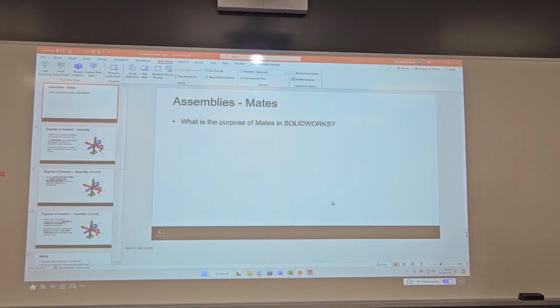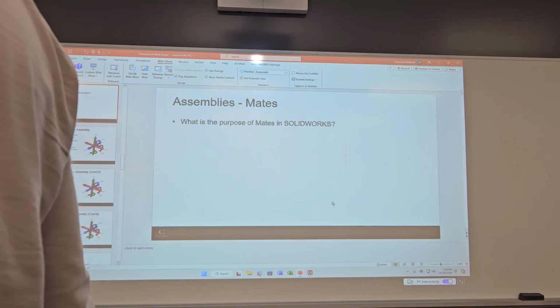Sir. Yeah. Okay, hold the face. To the top face. No, not that face. If you are in, then select the bolt face. So when you are making it concentric, you are selecting this face, not the head face. Then you select this face. Escape. And concentric. Okay. Now you select this face and then bottom face, so that it will line up with the faces.